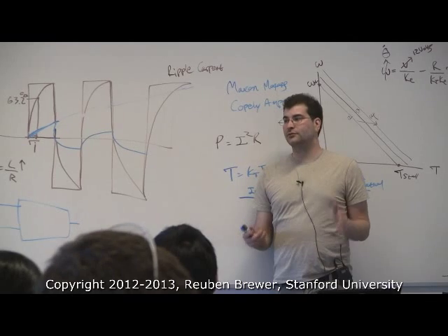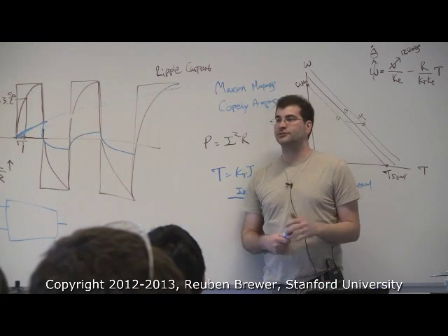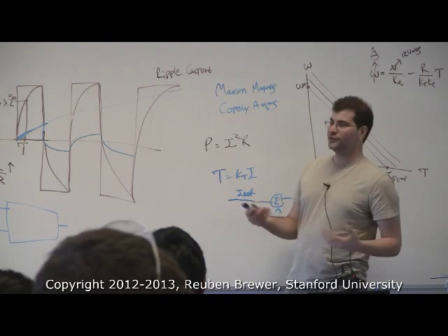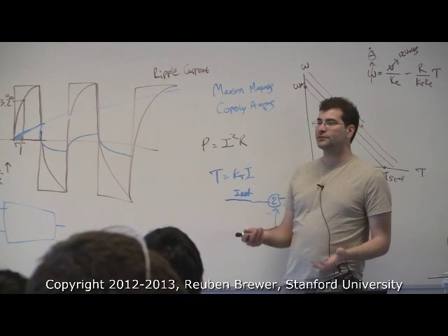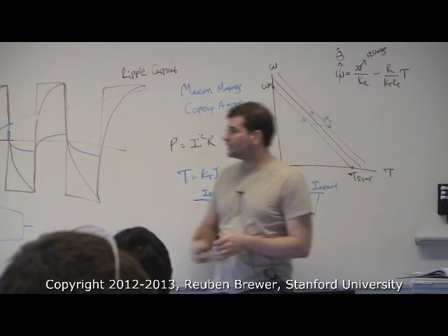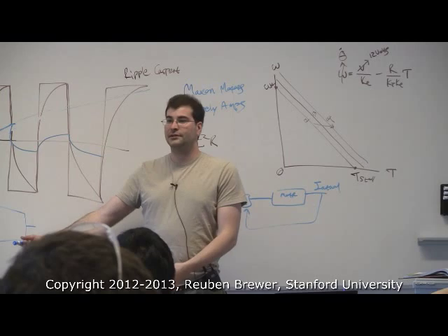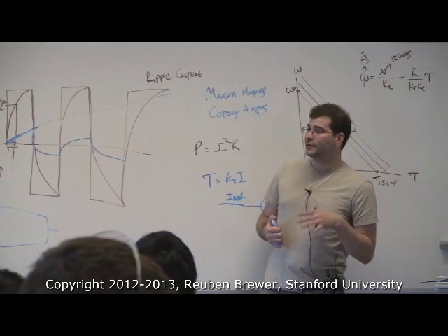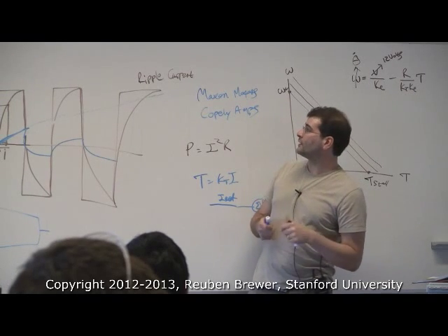Please, don't build your own motor amps, especially if you're doing force control. Everyone who sees the equation says, hey, I could screw with R. Sure, you could screw with R, but there's no reason to. Building robots is really hard, and there's no reason to start screwing with variables just because it appears in the math, just because you can. What I'm teaching you is the simplest, easiest way to get running and do things.